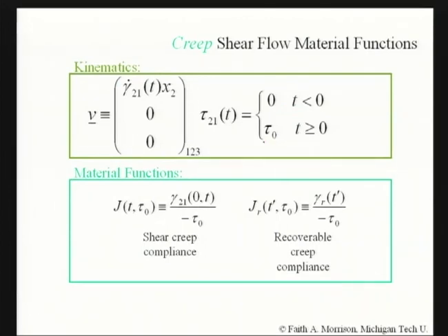Now what's going to happen if I apply a constant stress to the sample is it's going to start to move. It's going to start to, in fact, creep along, which is why this is called creep. But it's not going to move at a constant rate. If it's a Newtonian fluid, actually it will, and we're going to derive that. But if it's a non-Newtonian fluid, it's going to take some time to get to steady state. And we saw that in the movie, in his creep experiment in the movie. If you remember this flow here.